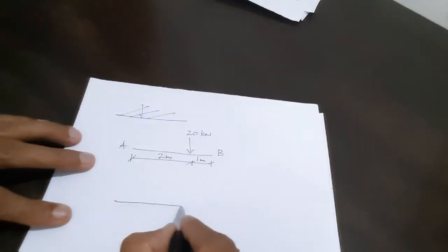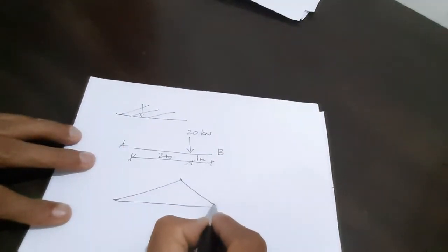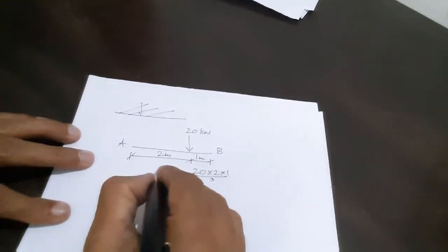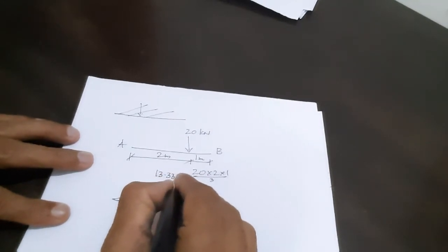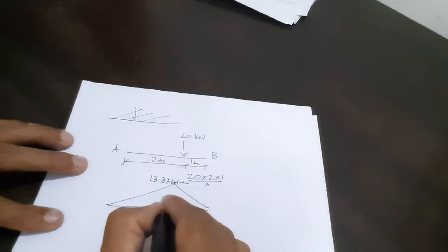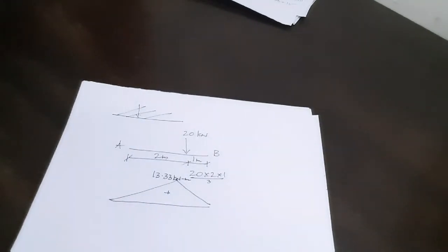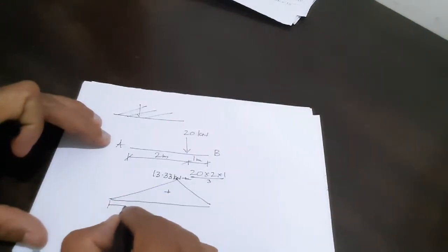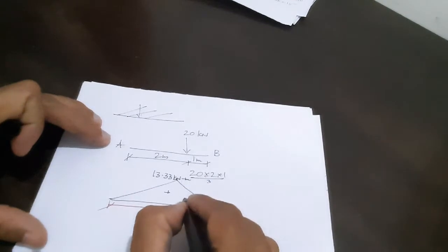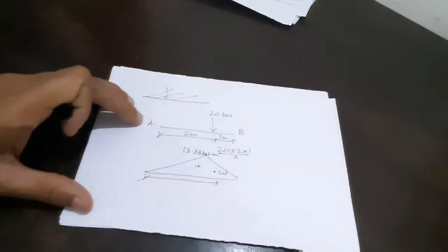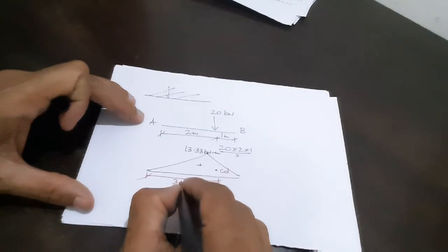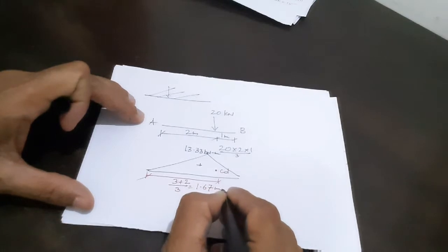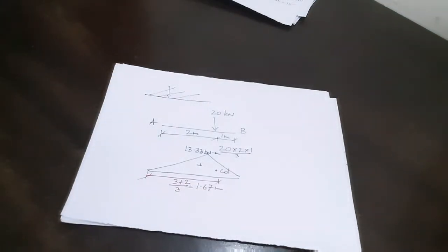I know the bending moment diagram, very simple. The bending moment diagram will be eccentric like this. It will be 20 into 2 into 1 divided by 3, so that is equal to 13.33 kilonewton meter. Simply supported bending moment diagram, and position of centroid from the left hand support, because AB is a left hand span. So position of centroid from the left hand support in this bending moment diagram will be, this is centroid, 3 plus 2 divided by 3, that is equal to 1.67 meters. So this CD is 1.67 meter from left hand support.